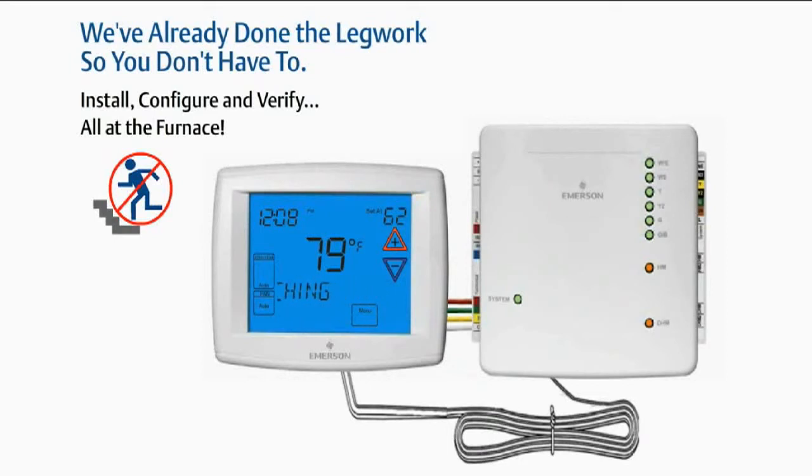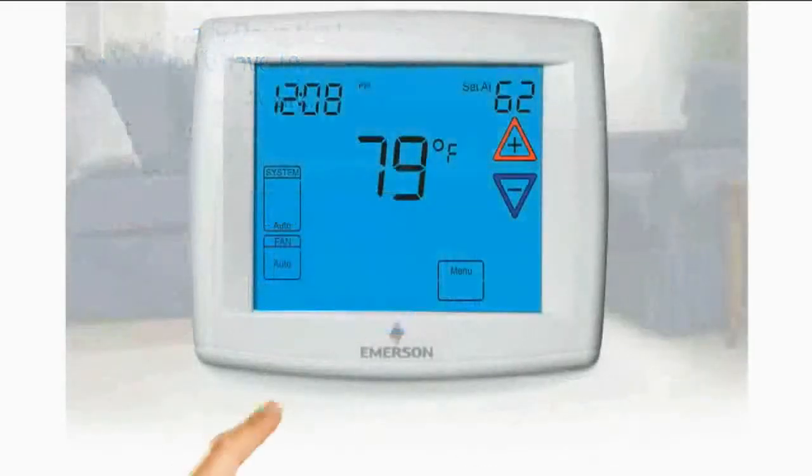Once 24 volts is powered to the control, you will see the word searching scrolling across the LED display. When the interface and the module communicate, it will then say control found. You can now enter and navigate the advanced installer configuration menu.